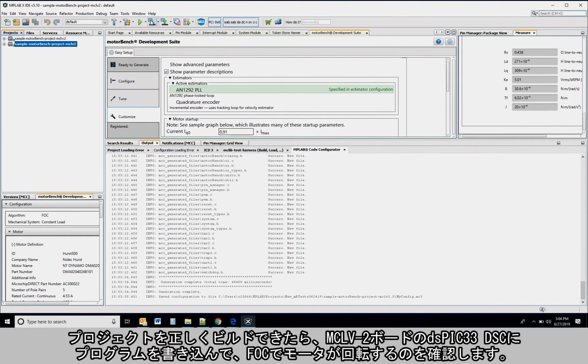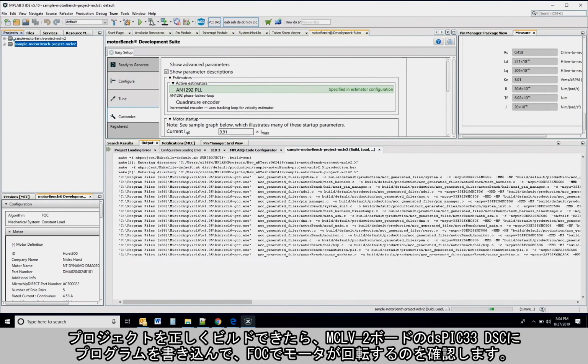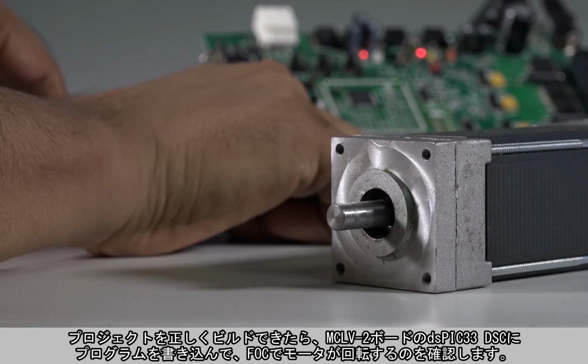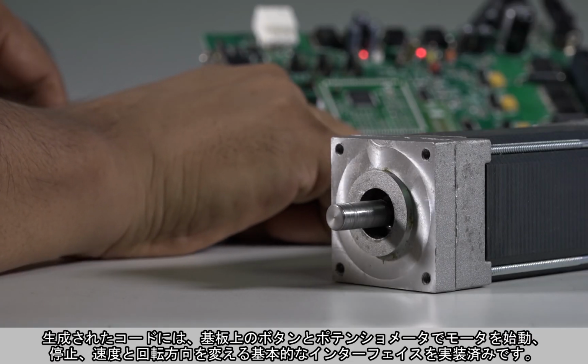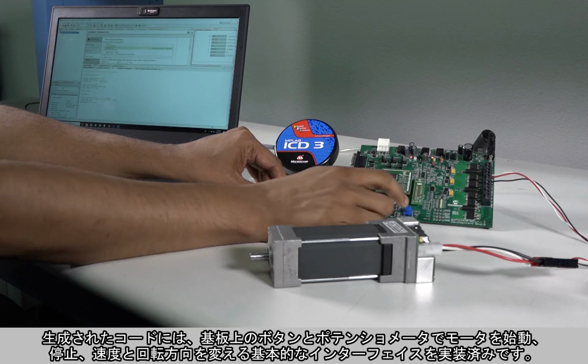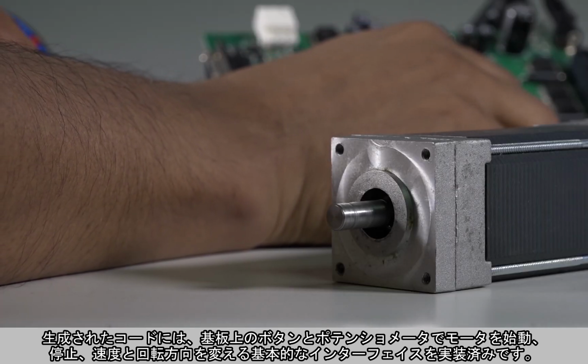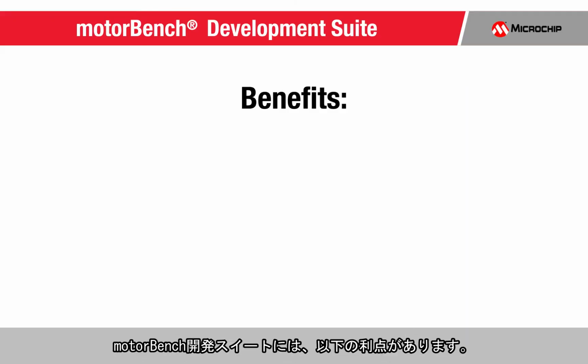After successfully building the project, program the dsPIC33 DSC on the MCLV2 board and see your motor spinning with FOC. The generated code has a basic interface to start, stop, and vary the motor speed and direction by pushing the respective button or turning the pot on the board. Now that you have successfully spun the motor, this project serves as a good starting point for developing your custom application.